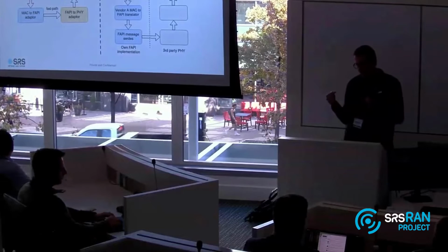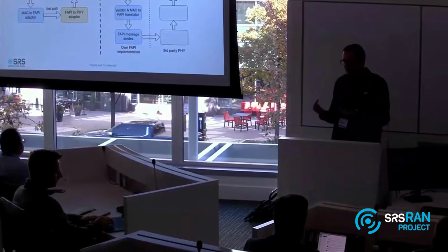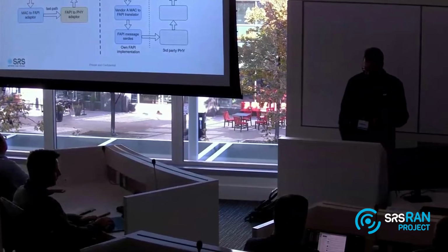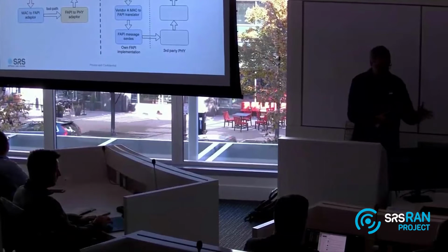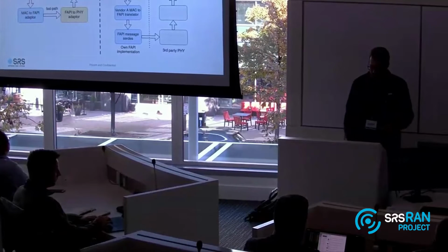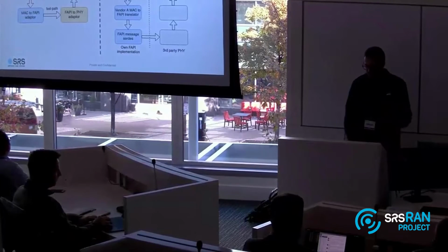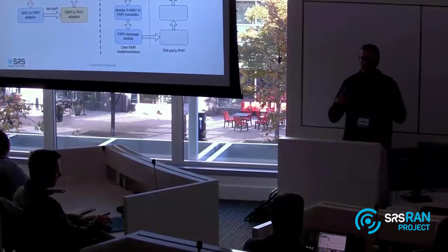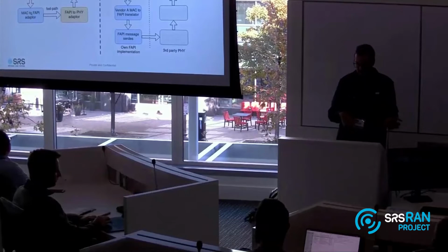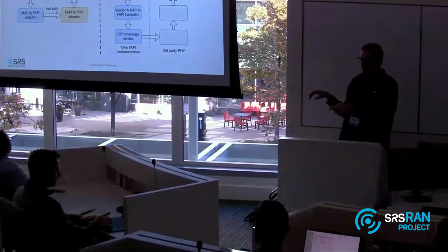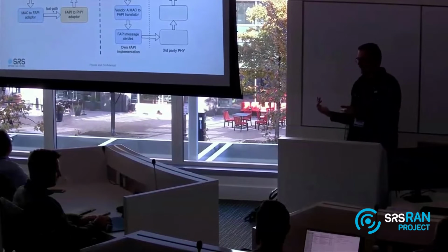Sometimes you have in your embedded board, I don't know, shared memory, serial interface, whatever. What happens when we are running the PHY and the MAC in the same machine, like we do here? We just cut at this point. We do what we call a fast path, and the MAC, from that struct that it was generating, this MAC to FAPI adapter just essentially copies. It converts the struct into the struct that the PHY understands.